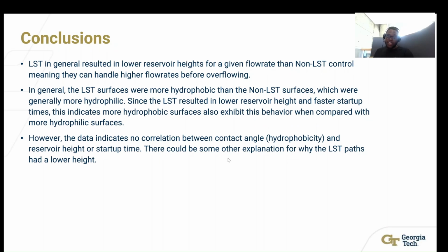There could be some explanation for why this correlation wasn't found directly with the contact angle, but during our test, we did find that the LST was generally helpful in maintaining the lower reservoir height and in general better water evacuation. So that's a summary of what we've been working on so far in the project.